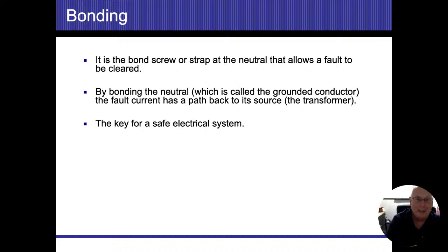So as I follow that out, if I run into a junction box on my ground path, I should be suspicious. Those are going to be the areas that I'm going to open up. And if you get inside that thing and you see your GECs are spliced together, that's a problem because we're not allowed to splice those whatsoever. If they're going to be in conduit, they have to be in conduit by themselves. We can't use that raceway to share with other electrical wires. They have to be standalone all by themselves.